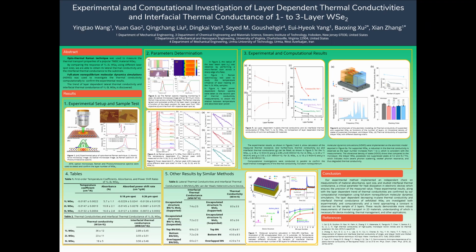In general, the laser is focused on the center of the suspended flake area, and the heat is transmitted along the radial direction away from the center of the flake. And we are considering the measured temperature, laser power, laser spot size, and absorption coefficient of the sample.